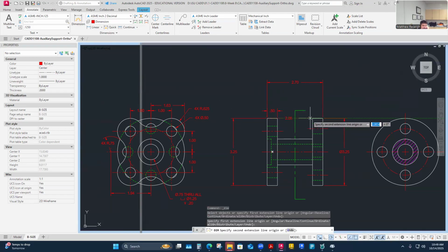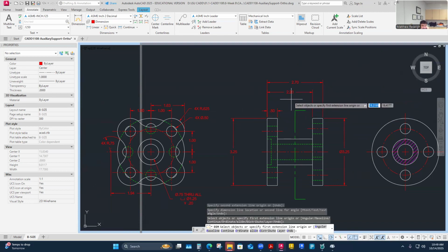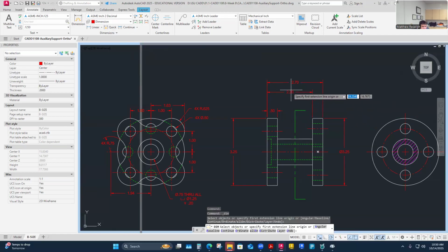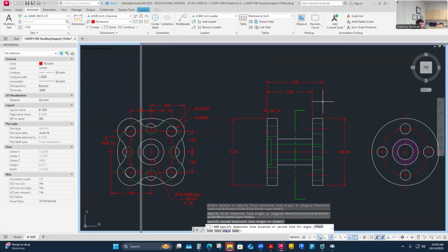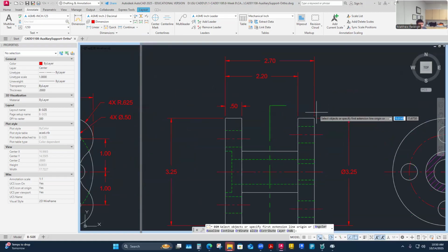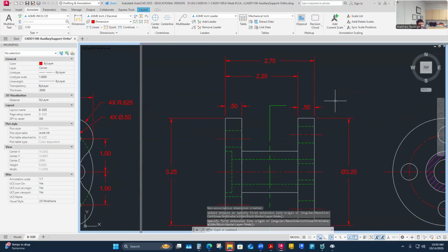maybe I could put two dimensions here. This one here is a nice to know, and maybe this one is more controlled. That one's on our print for sure, and it doesn't mean it necessarily has to show up on my drawing, but this could become a really critical dimension. And I still don't feel like it's redundant to say, well, then I would also have this, and then I can do the math, and maybe this becomes a reference dimension. Sorry, I pulled that wrong, but this might be a good candidate where I would add this dimension.